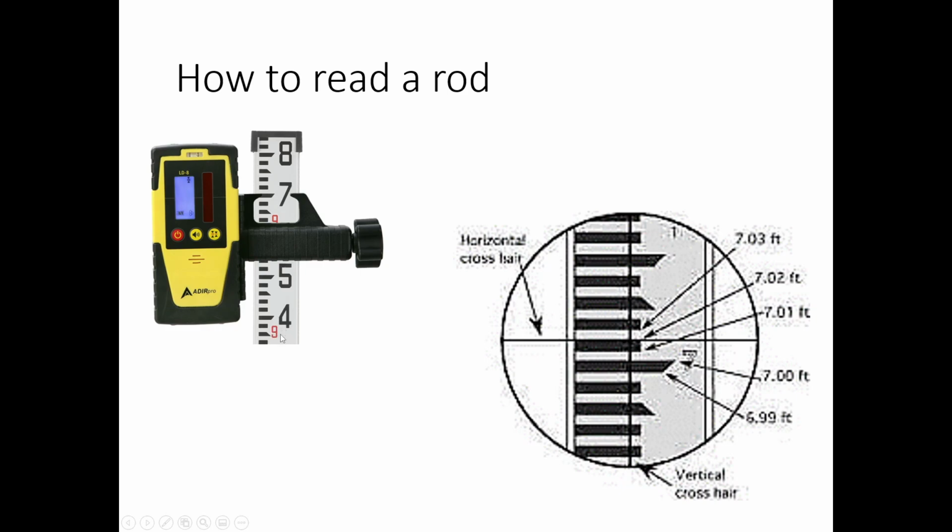And then you'll see the actual tenth mark, basically where you're at in here. Depending on the rod, it could be either way. Some are in tenths and some are in hundredths. But we look here, actually, I'm sorry, that was right. These are in hundredths, because if you look here, the red number is actually what foot you're in, and each of these black numbers are the tenths.